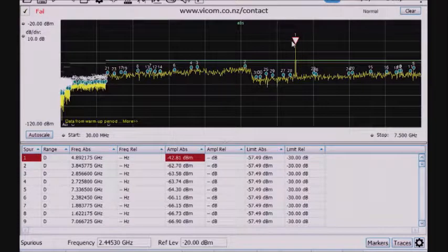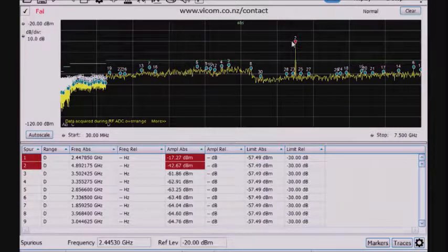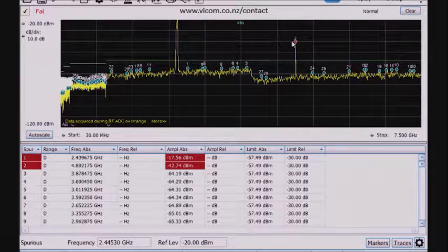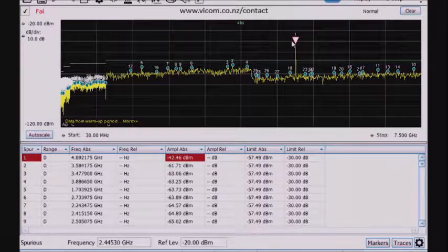But in general, a CISPR peak-based search is a much faster test and a more conservative test to make sure I have good confidence to go past final EMI compliance. So I don't waste time in the compliance lab. I can figure this out in my own bench, provided I have enough shielding and not any other signals present that might cause me to fail the particular test. So hopefully that gives you a little better understanding of how to use a spectrum analyzer to perform EMI pre-compliance checks to give you better insurance for passing final compliance.